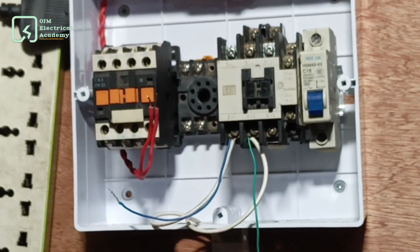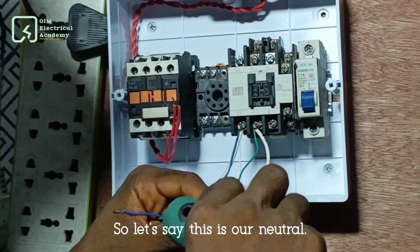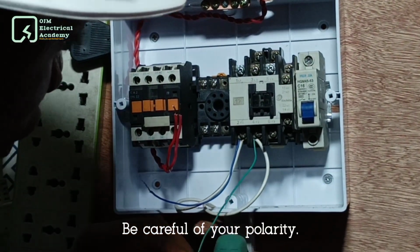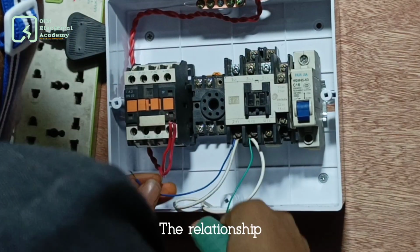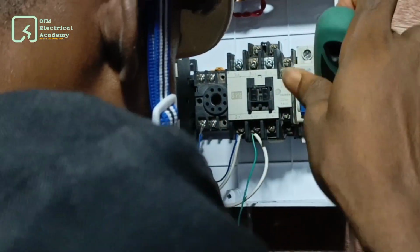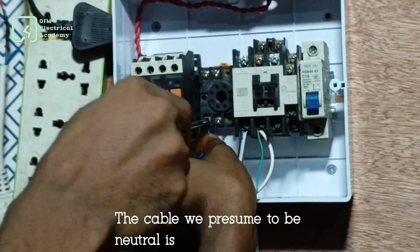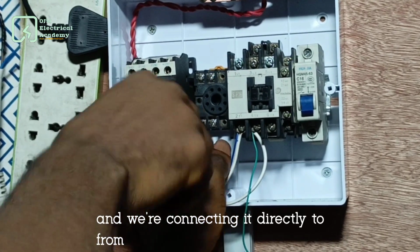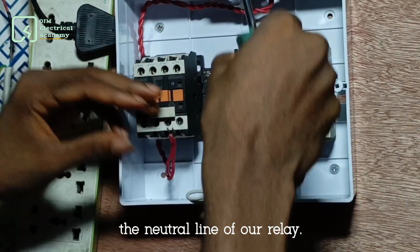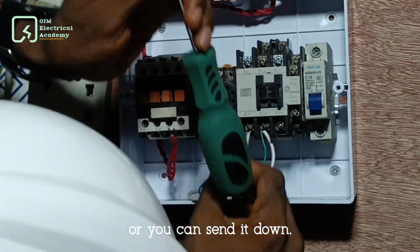Okay, more wire. We are looking at our diagram and then making the connections. Let's say this is our neutral. Please be careful of your polarity. So it's connected to 7. Let's use that large one since it's closer. Connected to 7, then from 7 to the coil terminal of our contactor. The cable we presume to be neutral is what we're making connections for, and we're connecting it directly from there to the coil terminal, the neutral line of our relay. You can send wire here or you can send it down.